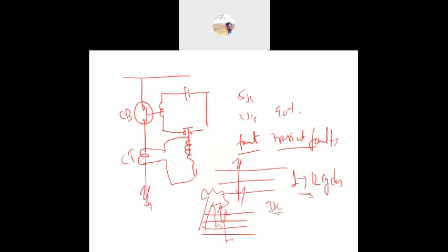The recloser should work at 15 to 30 seconds. Usually there are 3 reclosers at 15 to 30 second intervals, made to clear the fault. According to the reports, most of the faults are cleared at the first reclose, about 80% of them.